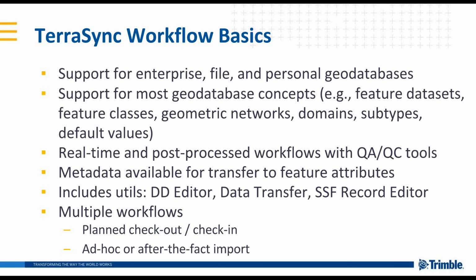Like what I mentioned before, that metadata is available for transferring back to feature attributes. As of the most recent release, we do include several core Pathfinder Office utilities with Trimble Positions desktop. So we include the data dictionary editor, data transfer utility, and the SSF record editor. They come as an installation option when you install Positions desktop, and they can use a license of Positions. They don't need a separate PFO license to use them.